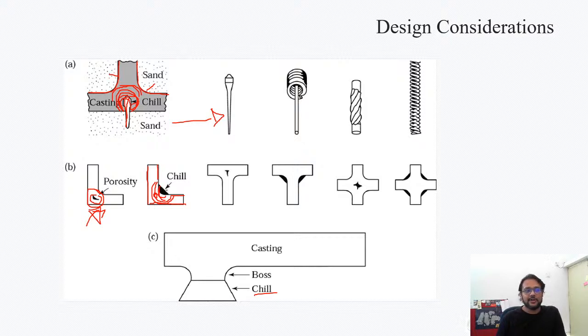Okay, later on, after the casting process is done, this chill becomes part of the casting, and this can be machined off as required. So these are other places where such a design thing can be put in. The shape of the chills are also quite different for different applications. Some are like this, some are the shape of springs and all, and it depends on the kind of